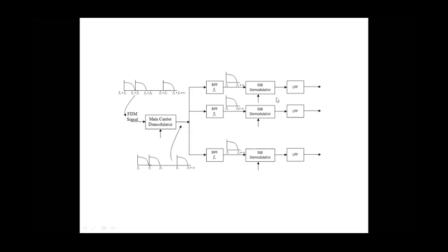So then what will happen to the output? You see, the output will be 0 to W Hz. Before this, they will be having some higher frequencies. After passing through low pass filter, it is limited to W Hz. So like that, at the output of each and every low pass filter, we'll be having again the same message signals which are generated from the sources. Isn't it? So this is how you can send number of signals by using frequency division multiplexing system or multiplexing process.